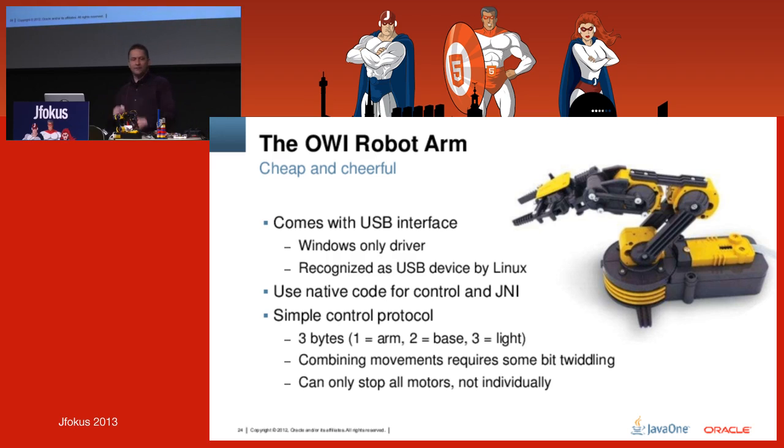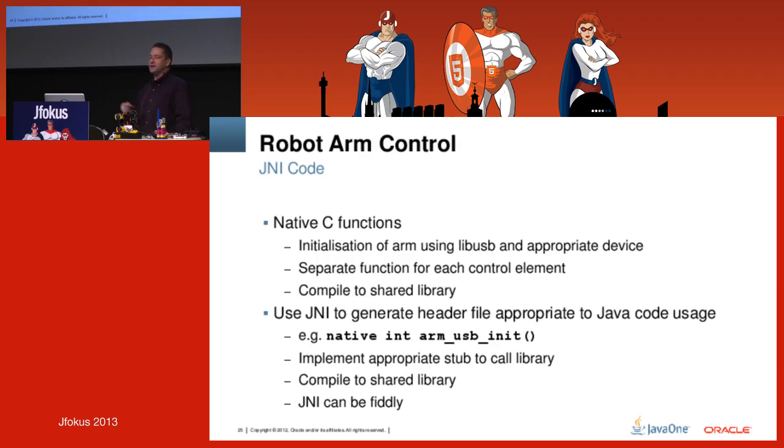I had to do a little bit of bit twiddling because you can't stop the motors individually. You have to stop them all at one time. So you can get around that by remembering which motors are moving, stopping them all, and then restarting the ones that you want to keep going. And that seemed to work quite well.